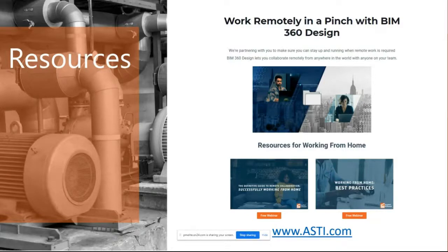Revit is limited to 20 miles in space, unlike CAD where you've got unlimited or 10 points of decimal precision, which is pretty vast. So the only caveat to the CAD file that I would add is make sure you clean it up. Purge, audit, flatten, W block it out of the original file, create a new version of it, purge out as much as you can, and then use that in your projects. So there is a cleanup process there.